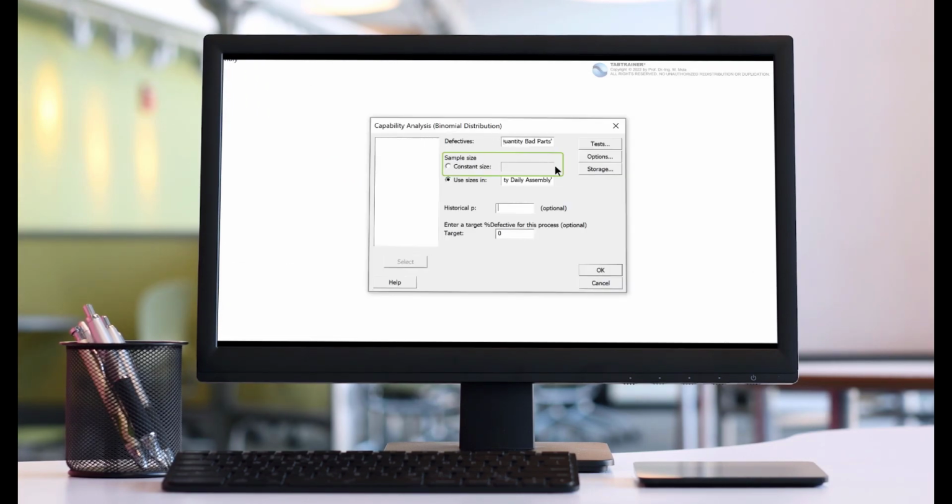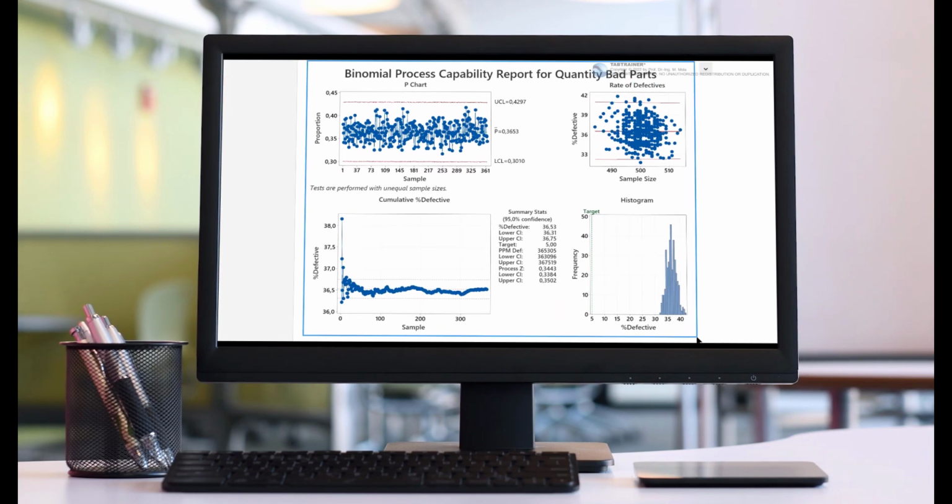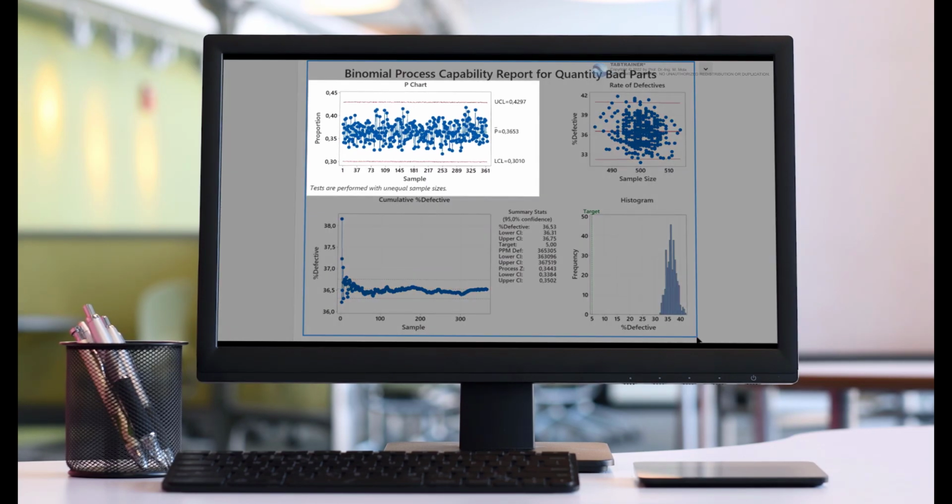The special feature of this process capability analysis is that we are no longer dealing with normally distributed data, as our quality attribute is present in the two categories good and bad, and therefore the statistical laws of the so-called binomial distribution must also be taken into account.